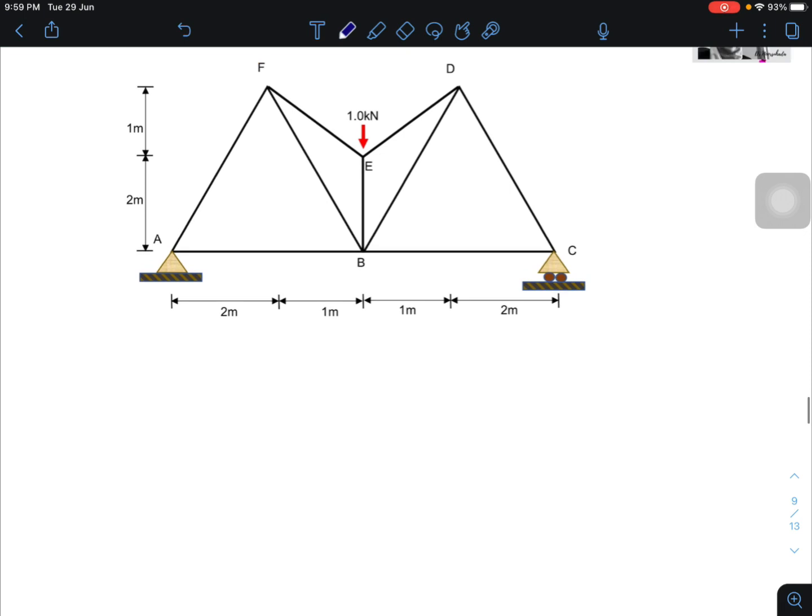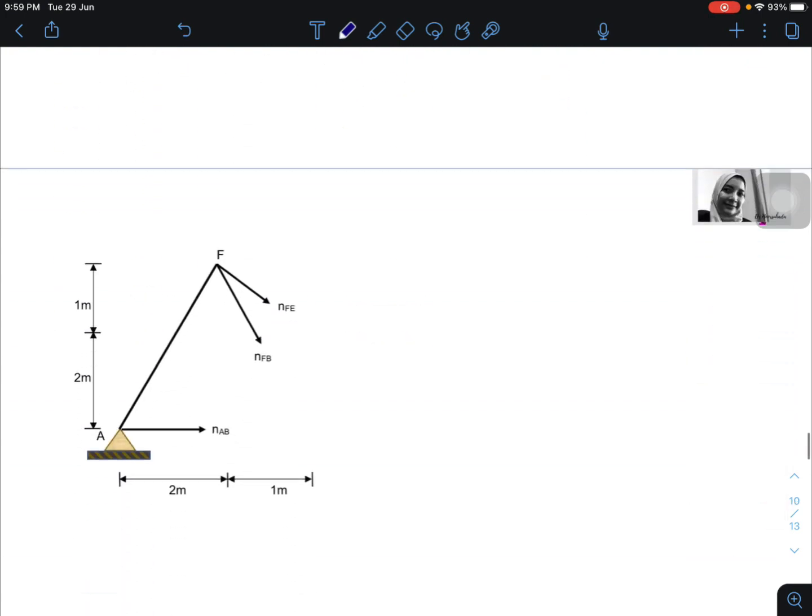After that, the second step is the determination of internal forces, or member forces, due to the virtual load. Okay, the force for each member due to this 1.0. And then this is the free body diagram. For this we use the same steps as for the real load.